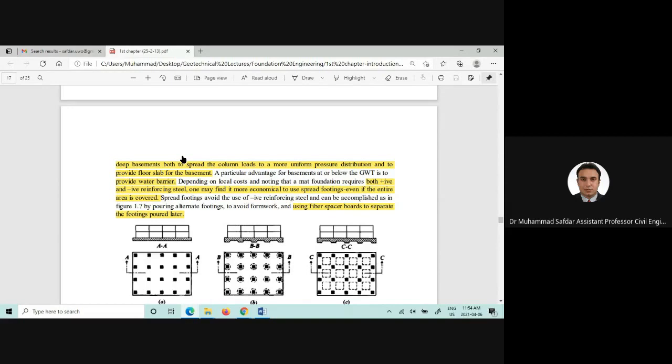So we are given a soil beneath the foundations there, and most probably the soil conditions won't change at all. So you need to perform the basic geotechnical tests, and then we need to perform the advanced shear strength parameter tests as well.